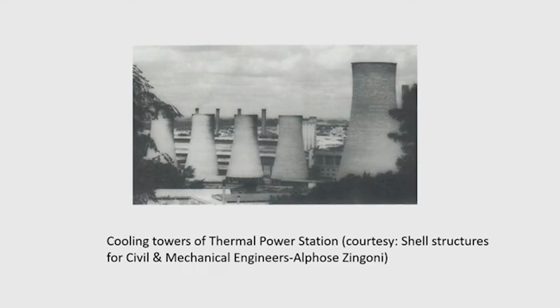We have discussed the membrane theory of shell, and we have seen that in membrane theory, the membrane forces, that is the in-plane forces N phi and N theta, and the membrane shearing forces N theta phi are significant.